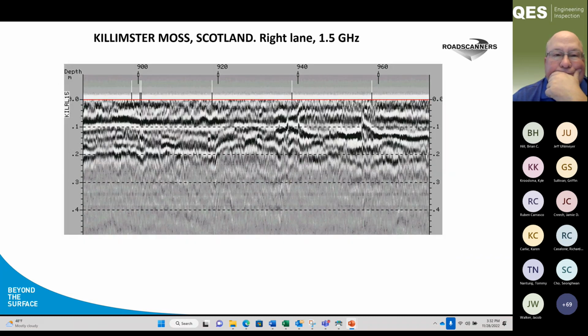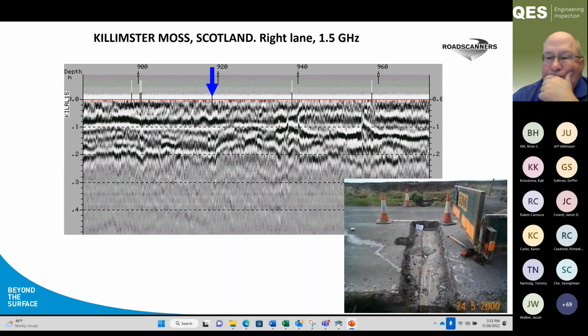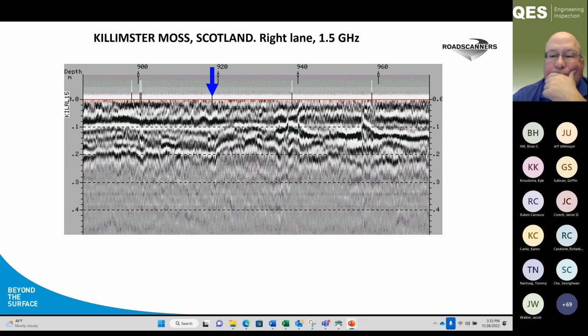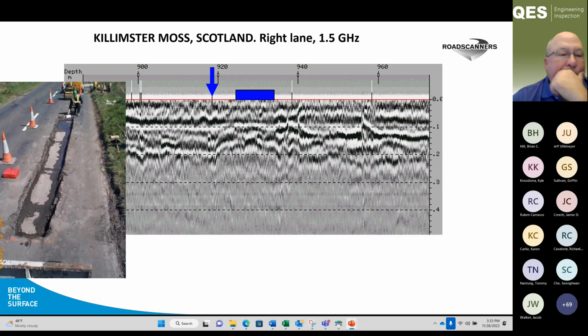Next slide. And here is another example, and if you click once, so what you see, Steve, the next slide, and click one more time, and here's a transverse crack, which is also very much related again, like a bottom up cracking stripping, and if you click the next one, and it comes from here, and you see really the main reason with the stripping is the moisture on the bottom of the asphalt layers. Next one.